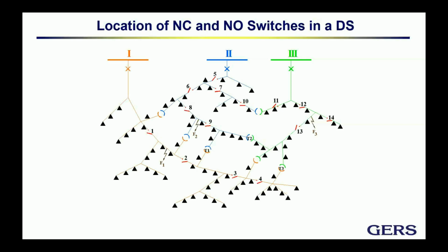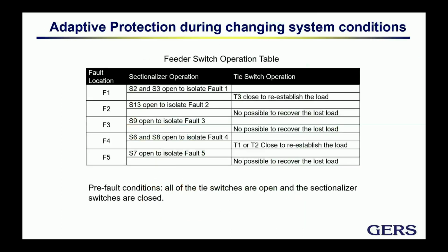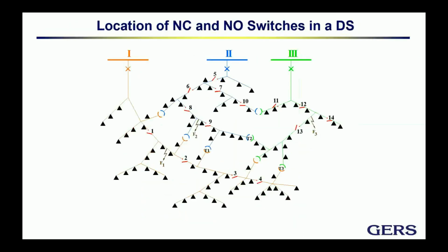So we have to know where the fault happened. We have different ways to achieve that. Once we determine that the fault was here, we just open the 2 closest section switches. Section because they were all closed. Third step, once we open these, immediately, without any latency, we can close the breaker here. Because we know that the feeder can, of course, take this load. Actually, this load will be a lot smaller than the original one. No problem whatsoever.